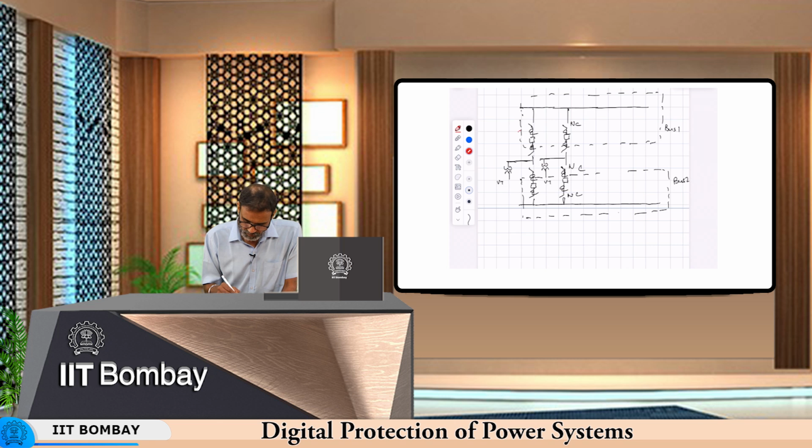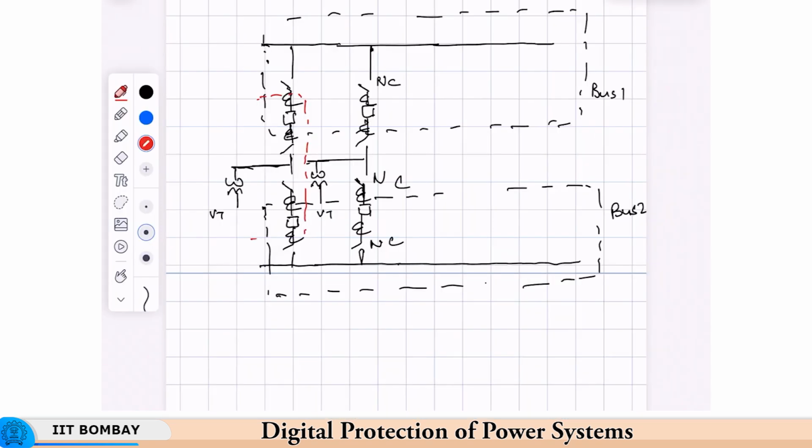So, for the line protection, because the current is flowing from either side, you will need a summation of these two CTs for the line. That is how the line protection will be done. You cannot rely on only one CT, because the current is flowing from both the ends. Now, before we discuss the other schemes, one important aspect of protection of a bus bar is stuck breaker.